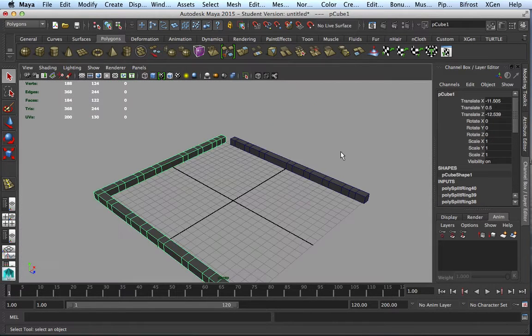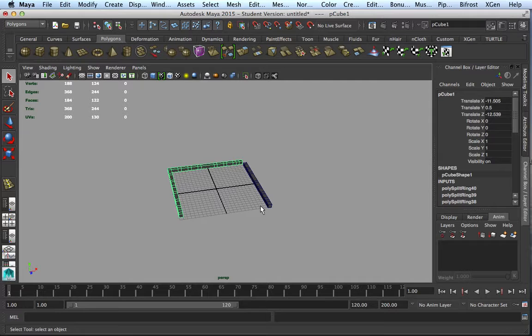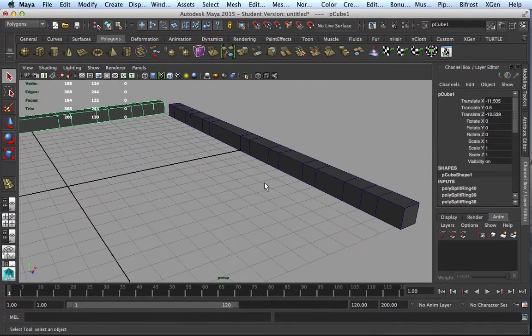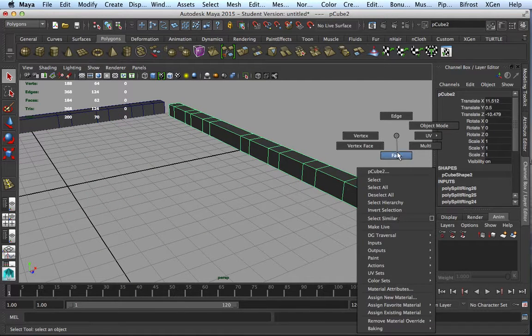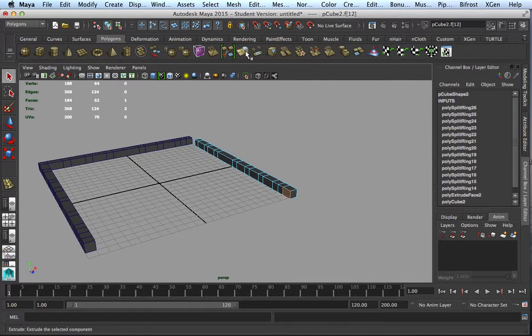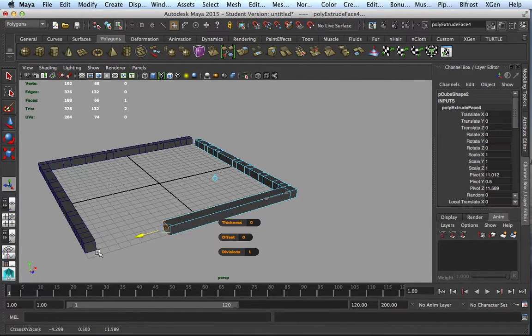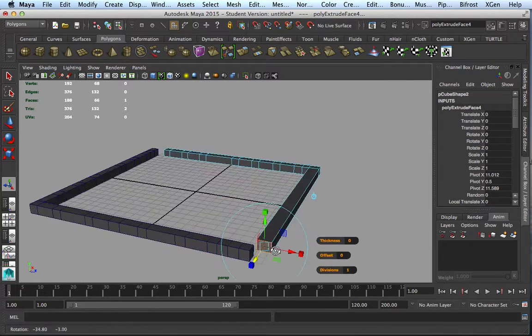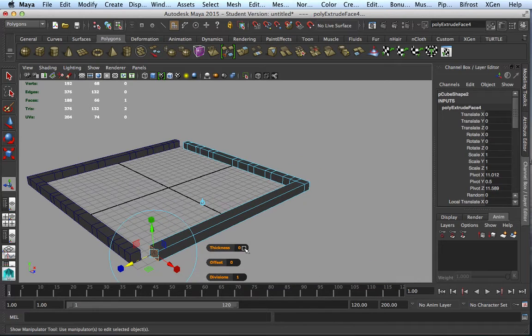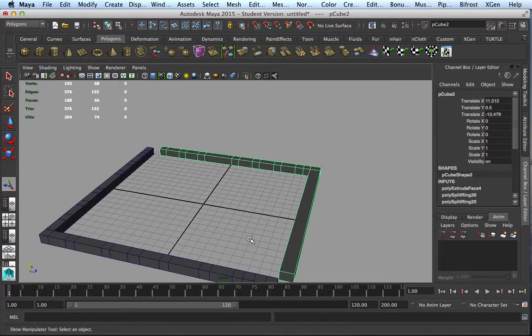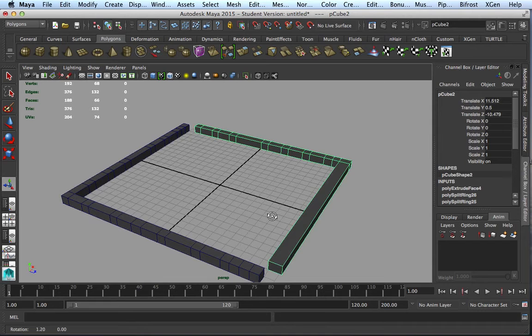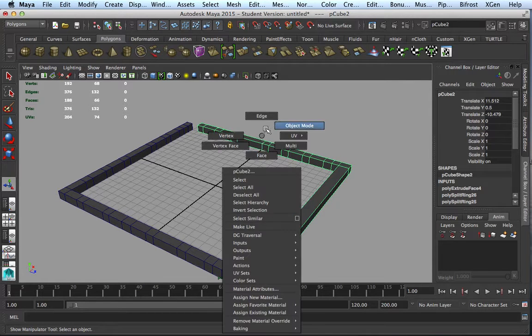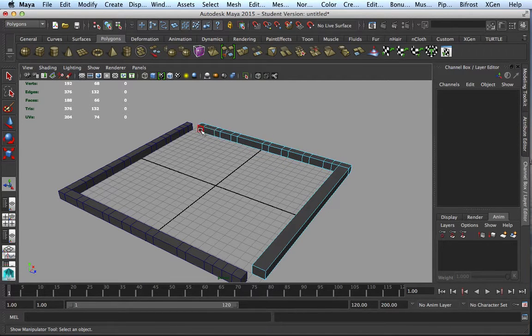I'm going to go ahead and build this other wall to close up this opening. So I'm going to select this cube, right click face, select this face, hit extrude, pull the blue arrow all the way over here to create the exit or the entrance. Okay, so there's 2 openings on either side of the maze. And again, you can go back in here and cut more edge loops. I'm just going to stop right now in cutting. I'm just going to go ahead and proceed. So right click goes to my face mode. I'm going to select this face.